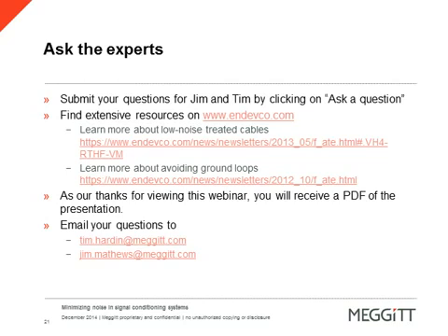I think they're trying to state they have one accelerometer and they would like to put it into two different signal conditioners. That's how I read the question. So I would use one accelerometer, one signal conditioner, take the output from that conditioner after you have a low impedance, high voltage signal, and then split it off. If you're going into two different data acquisition systems or analyzers, I would use the proper input-output grounding scheme of one amplifier, one cable, one accelerometer, and take that output and do with it what you need to do for multiple channel purposes.